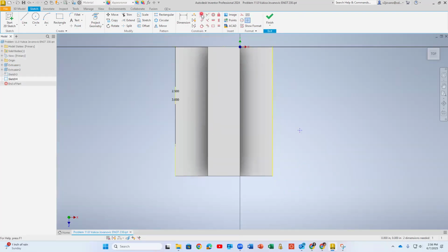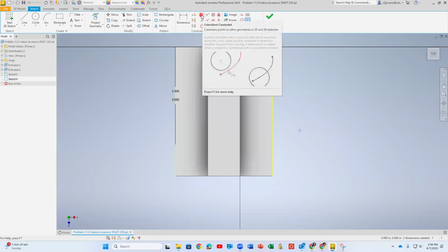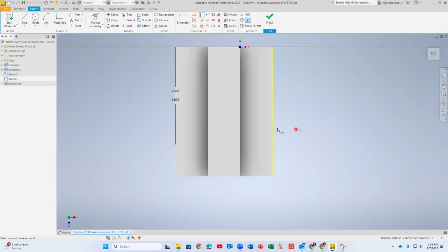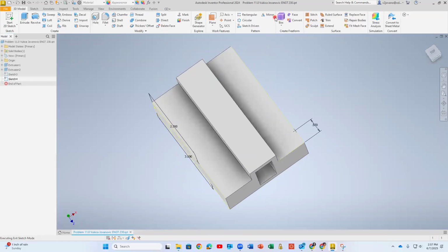And then I like to use this coincident constraint, and I will say, can I put this point here? And then all I have to do is add 1 dimension, because I said that that point, I like it like this, because if I change anything later, that point will still stay in that line and on that surface. And then before, you can just switch these back to invisible lines, you see. So now we created a point over there.